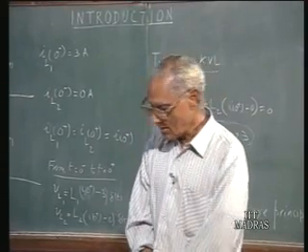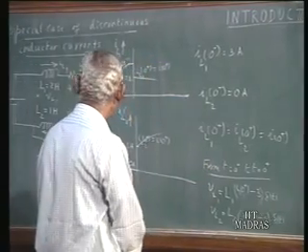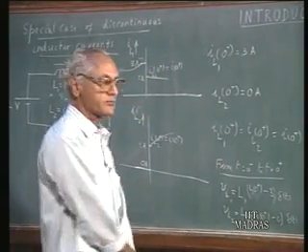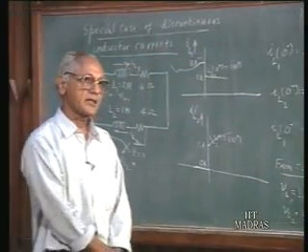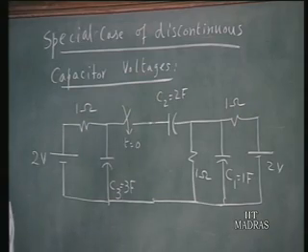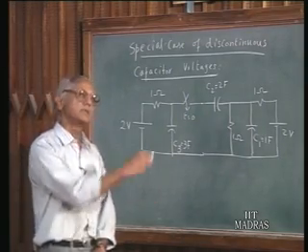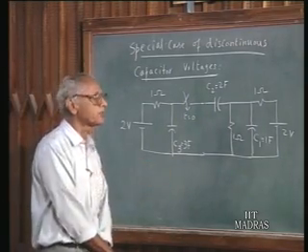Therefore, this is a particular case which one has to keep in mind whenever, as a result of a switching operation, a new constraint on inductor currents is brought about. Just as inductor currents can be discontinuous in special cases, we have to calculate the t equals 0 plus values given the t equals 0 minus values using techniques as we have seen in the last example.